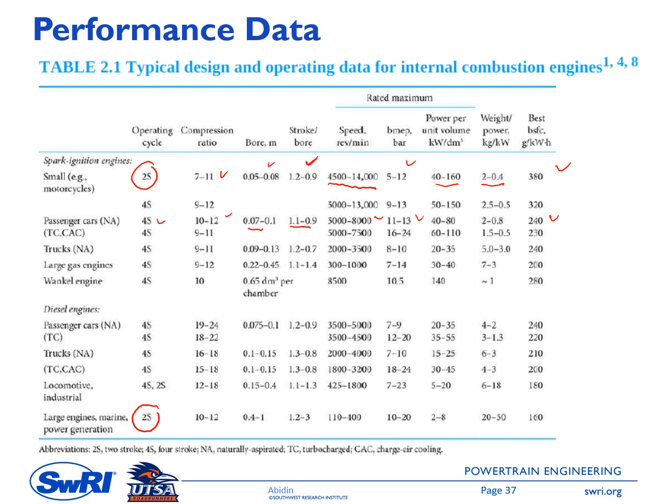And then if it is turbocharged, it's this line, this turbocharged. CAC here is charged air cooler, so it means we cool down the air after it is compressed inside the compressor of the turbocharger. So the goal is to have denser air, thus improving the amount of airflow and thus higher engine power.